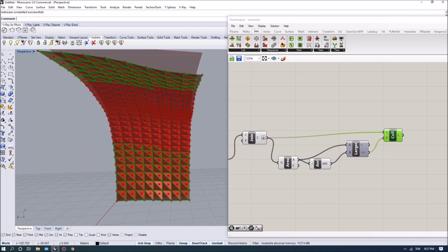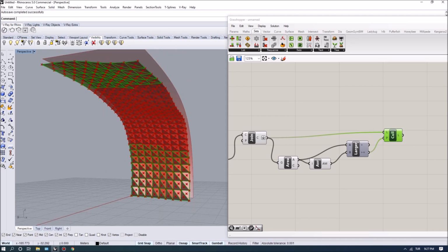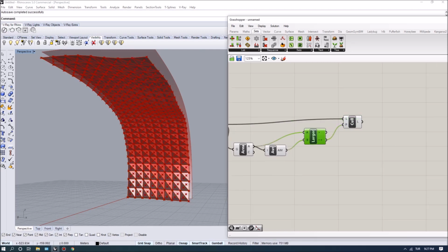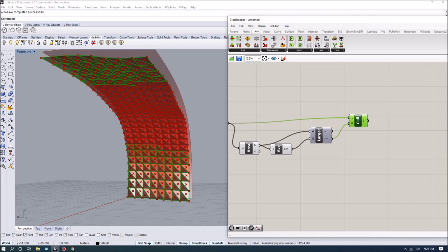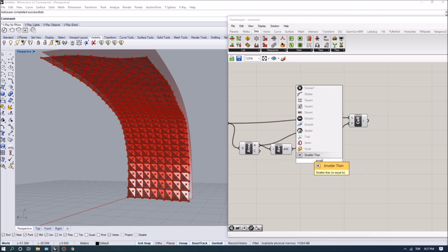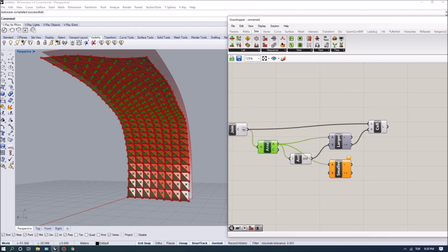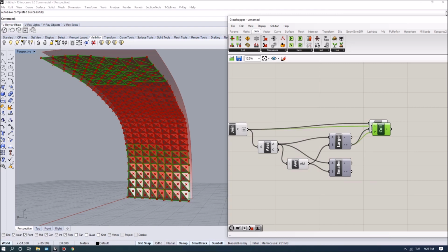So here you're seeing, because we don't have as much transformation, the larger tiles are located at the bottom and on top, and this middle is actually below average tiles. So the largest area tiles are located at the bottom and on the top. And I can find the remaining values by doing a similar operation, like smaller than. I'm going to compare now the areas if they're smaller than some value. And we can simply look for the smaller cases this way. And you can see that I can now select the smallest area triangles and the largest area triangles.